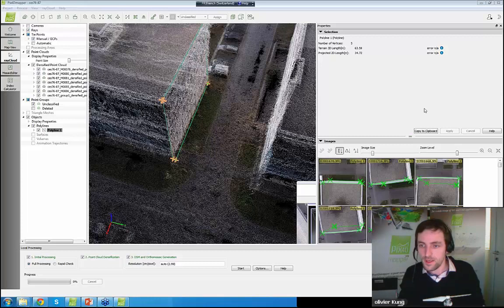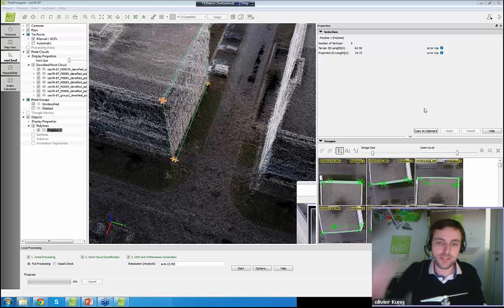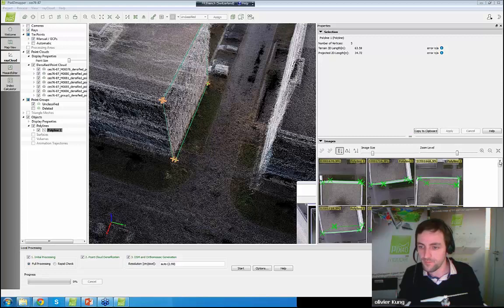If the mission ends in the middle of the flight, is there a way to resume where it left off? If the Wi-Fi is broken in the middle of the connection, the drone will keep trying to connect back to the Wi-Fi again, and in many cases it will be fine. It will just be a few images missing in the middle of the project. However, if this does not happen, or if you really need these images, then right now the only way is to restart the mission from the start.